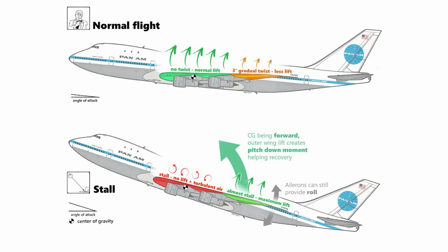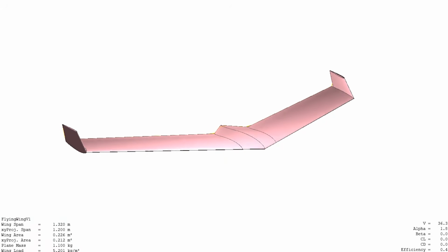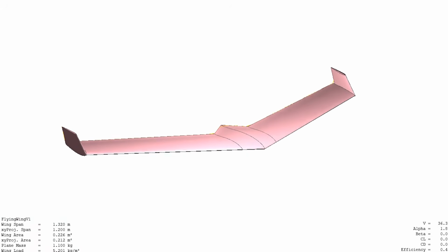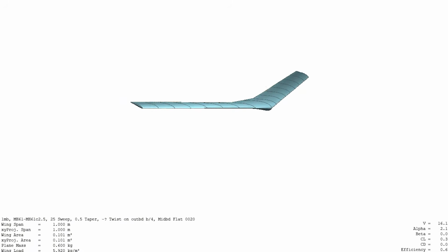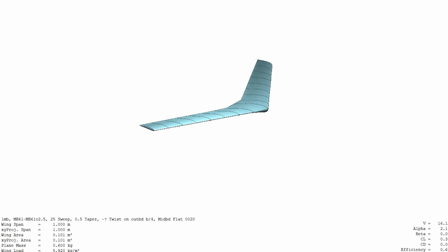And because there's no horizontal or vertical stabilizers here, pitching and yawing stability must be achieved aerodynamically or forced through control surface actuation like in elevons, rather than geometrically simply by a tail far from the CG. Because the control and stability characteristics here differ from traditional aircraft designs, the design for stable and controllable takeoffs and landings can be challenging, and it can be particularly difficult to decouple any yaw roll or Dutch roll coupling or roll pitch coupling for tailless aircraft, especially in those without a fin.